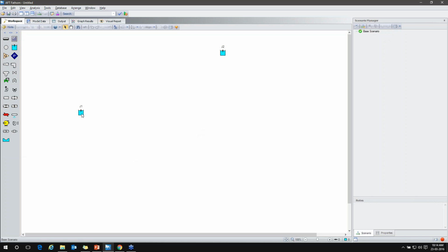Since we have a case where a reservoir at the lower level is pumping to a reservoir at a higher level with the help of a pump, this is how my model looks. So let's connect it with the pipeline. Over here this is the pipe drawing tool with which we develop the pipeline. Just click on the icon and route the pipelines from the junctions. When developing the pipelines, on J1, J2 and J3, we just route the pipelines on top of these junctions.